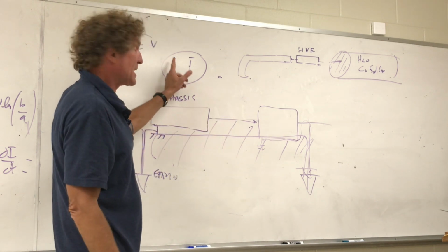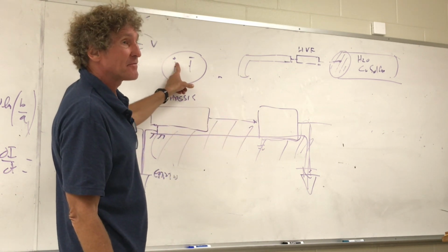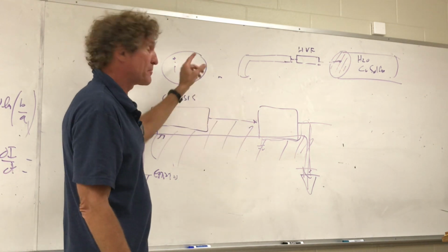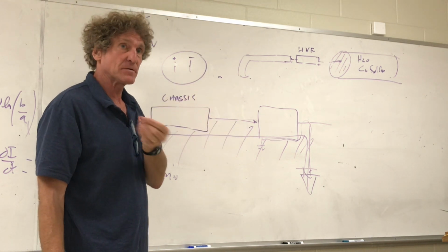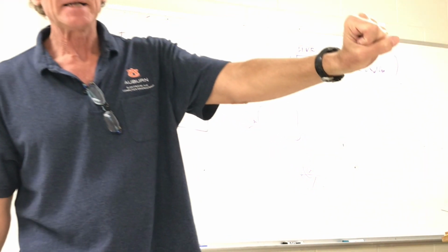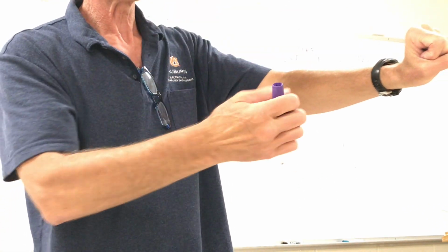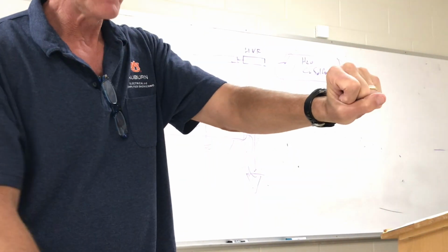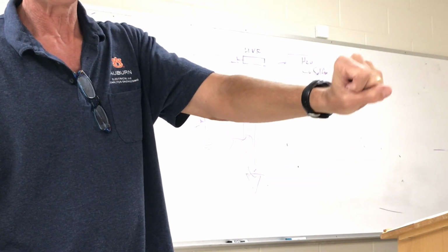But that plus right there will also drive current to the earth ground. This negative point is referenced to ground. Do you follow me? So if I'm grabbing a washing machine and say the negative return line gets broken off for some reason, and I'm grabbing it, that current will try to go through me to the ground. It can kill me if it's high enough voltage.